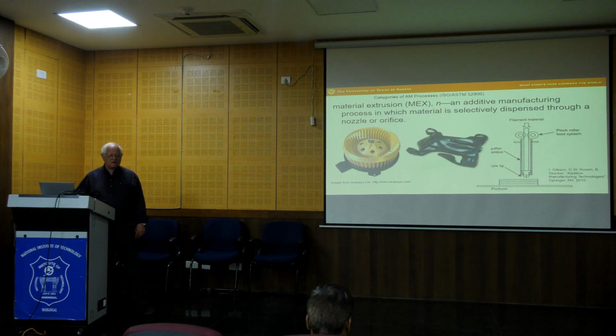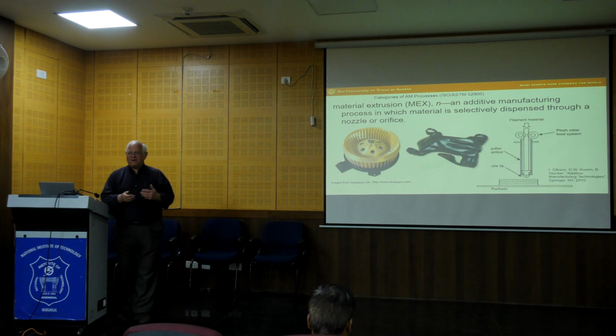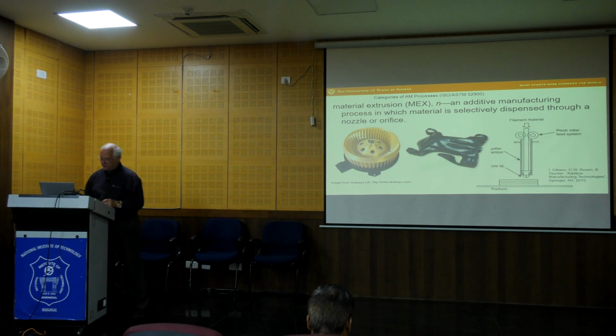Generally the properties are not the best. ABS is a good material. The Ultem material is very good in terms of properties, but the general materials, the PLA, are not particularly outstanding in terms of the properties. So we see there are some service applications for this technology, but generally these are for what we call form and feel, something to look at, but not necessarily to expect particularly good properties for applications.